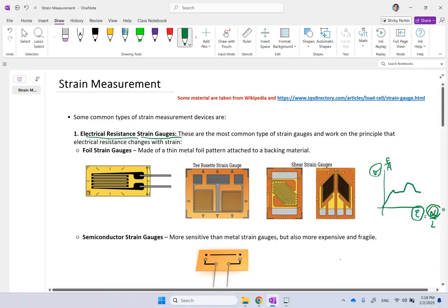And if you know the resistance of any material, that's the specific resistance, right? And then times length divided by the cross section. So if you make the length longer, you're making the resistance larger. And for that reason, it's a linear relation, which is the best kind of format, because if the relation is a one-to-one linear, it's the easiest way to calibrate your gauge.